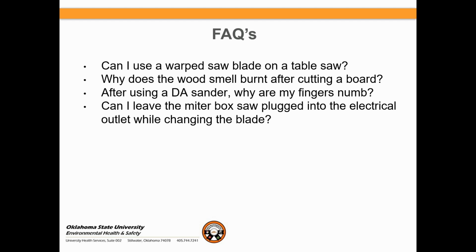Can I leave the miter box saw plugged into the electrical outlet while changing the blade? And the answer is what? The answer to that is no. Any type of blade, any type of drill bit, if you have to remove it, doesn't matter if it's from a cordless drill or from a wired tool, let's say a Sawzall for example, make sure that you unhook or shut off the power, please, and have exclusive control over that cord at all times.